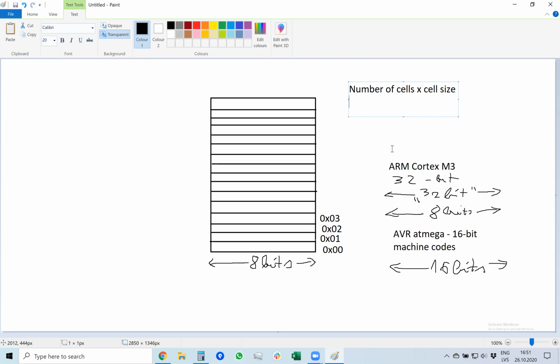For example, 1024 times 8-bit, which says that each memory location is 8 bits, so it's a regular 1-byte memory, and the number of such locations is 1024. We would say that its size is 1 kilobyte, but it doesn't tell you the structure. So 1 kilobyte doesn't tell you all of the information. So the important part is that it's 8 bits in each location and 1024 locations.